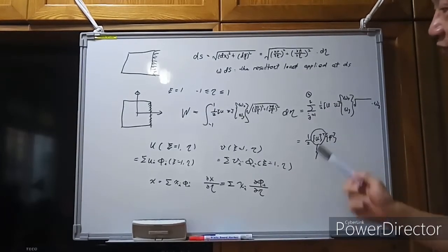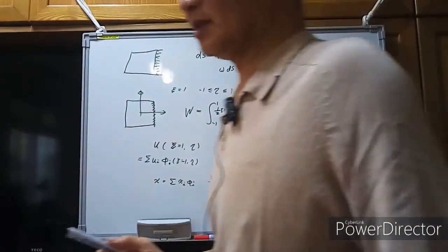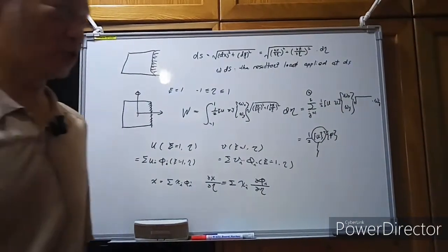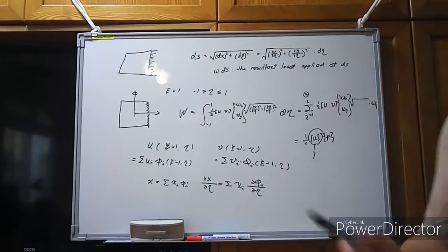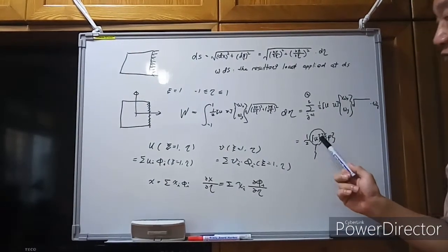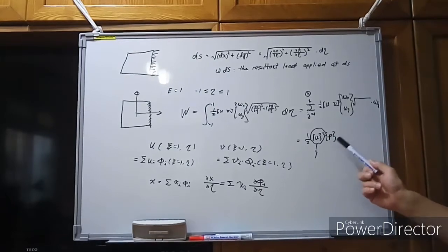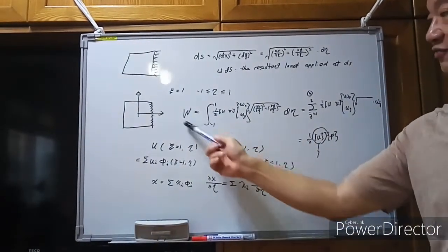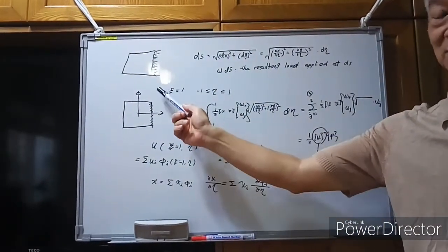Under the p vector, they are the so-called equivalent nodal loads. So if we multiply the nodal displacement of this element by the equivalent nodal load vector p, then you can get the same value of the work done by the distributed loadings.